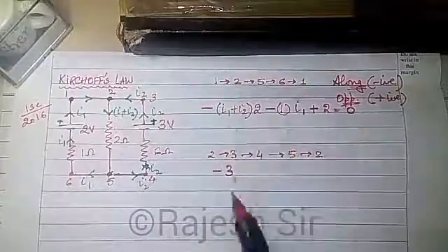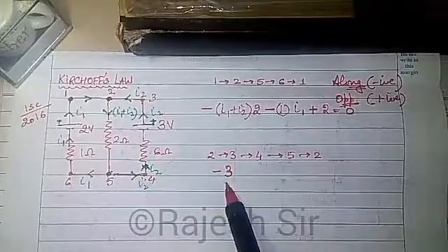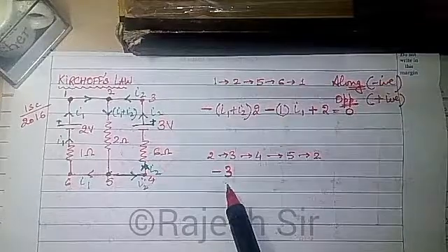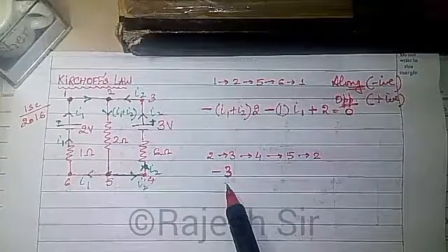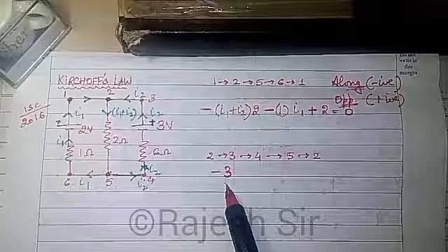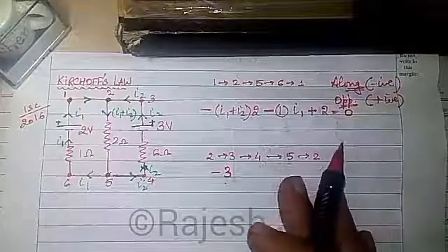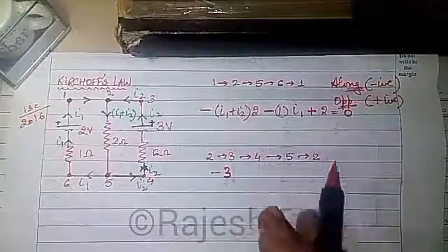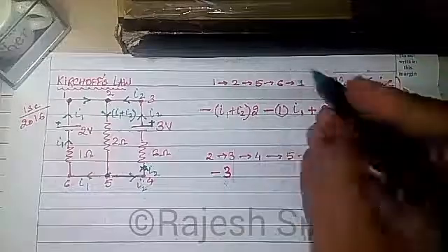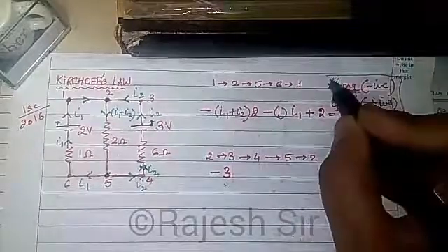When you are writing down the potential drop of the battery or the EMF of the battery, it is going to be independent of the current flow. You don't look at the current flow. You look at the current flow only for circuit elements.